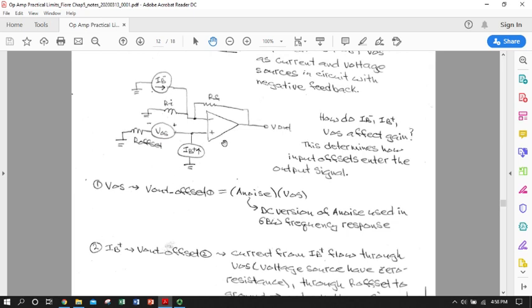In terms of the output, let's remember it's the output we're measuring. We've got an amplifier because we needed to amplify a signal, so we care about what's coming out at the output. We only care about the input insofar as it affects the output. So let's define a V output offset due to error source number 1, which we're going to say is VOS.